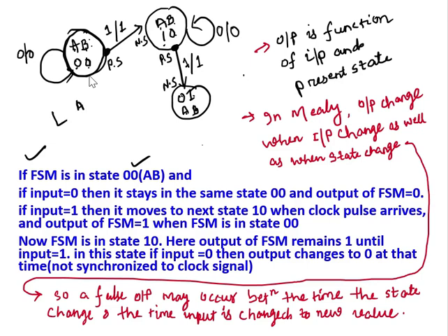These are outputs of a flip-flop, right? A is the output of a flip-flop. These are state variables. Again here it is written B, and again it is a state variable. So 0 0 means we have two flip-flops. This A is the output of one flip-flop, and B is the output of another flip-flop. So here we are using two flip-flops to represent this Mealy machine.